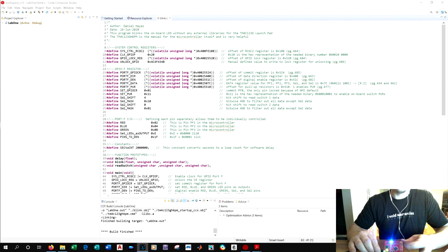And when it's done, I can push switch 2, and now I've got the blue LED blinking. And just to show you how the interrupts would work, I'm going to hit switch 1, and I'm going to hit switch 2. Notice that my blue LED doesn't blink, and that's because my code has to finish before it can start reading switches again. And there you have it.